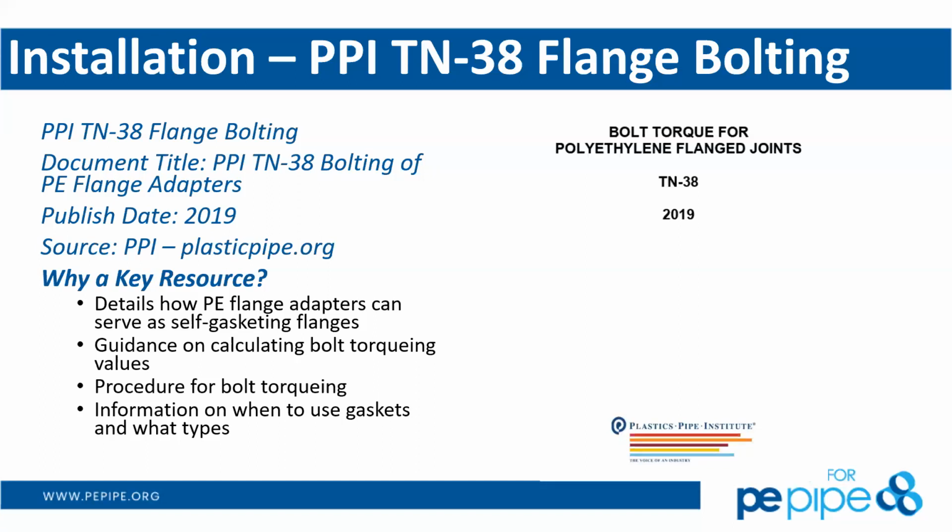So absolutely, yes. You're going to have to connect a flange to something at some point in time on a system. So on polyethylene, we use what's called a flange adapter. It's a machined usually or molded piece that creates the flange. That is typically butt fused to the end of the polyethylene pipe using the typical butt fusion process. And then it can get flanged up with a backing ring and bolts, just like any flange, to an appurtenance, such as a valve or whatever else you may have that you need to connect to.